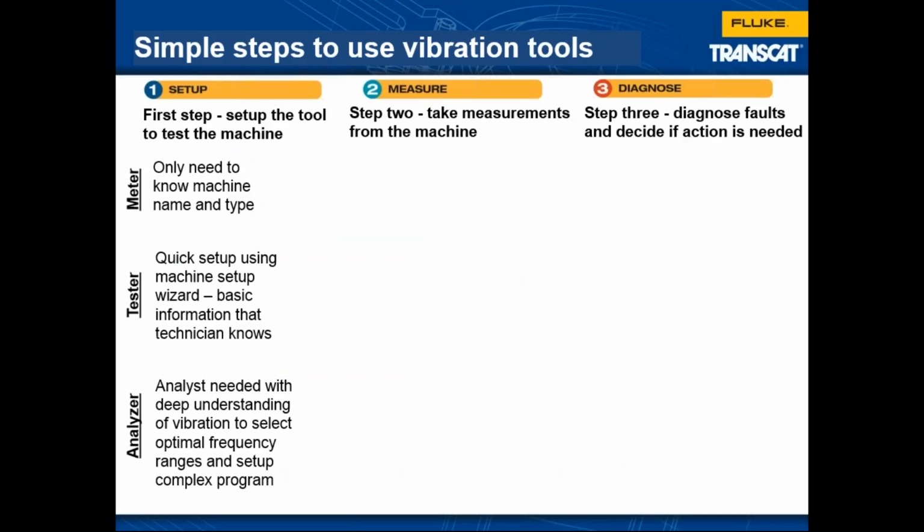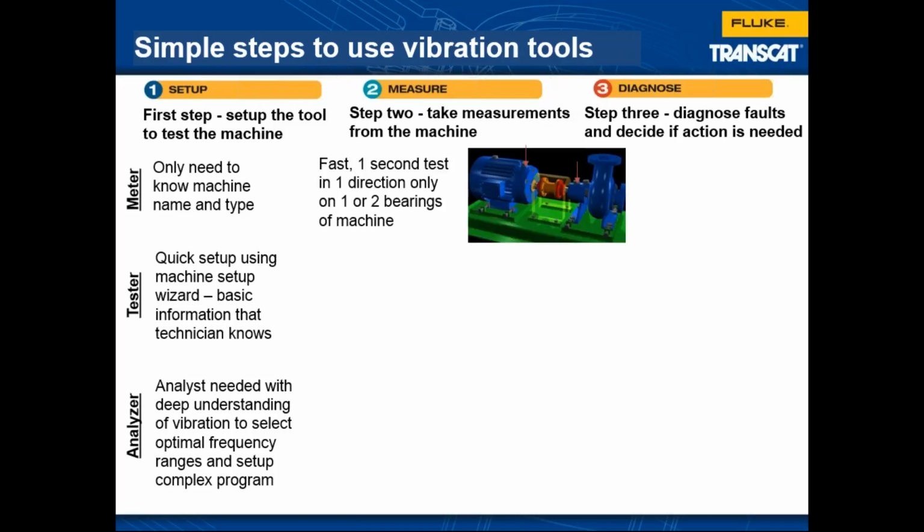So we've talked about the vibration meter. The vibration meter is simply going to take an overall vibration reading. Think of it like the nurse. It's going to simply tell us, is the machine good or bad? With the vibration meter, it's easy to set up. You take a quick overall vibration reading. It takes a second or two, and it's done.